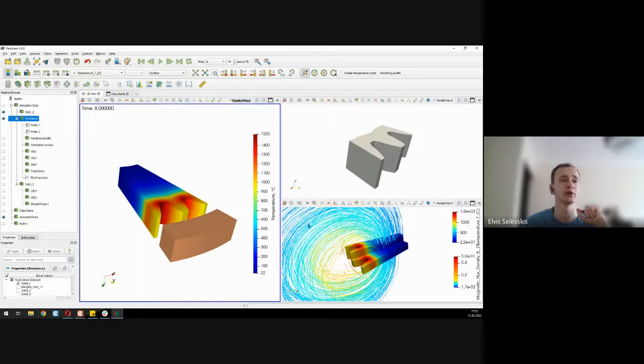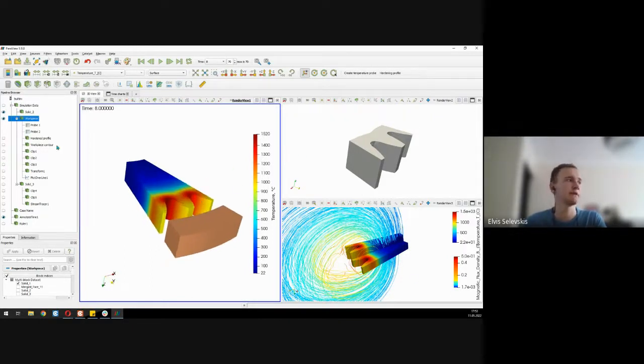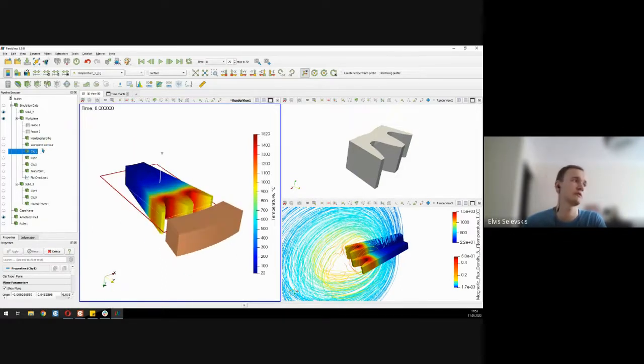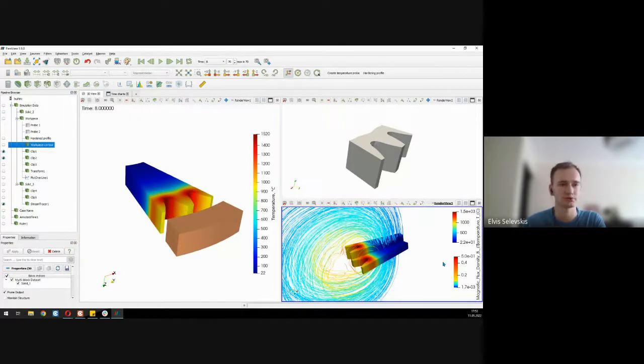One thing to point out: when you go into that save animation option, make sure that everything here is exactly as you would like it to be. If you have some kind of slice filter and you still have your mouse on that clip filter, this red box will also be extracted out in the results. So that's usually not what we want to see.